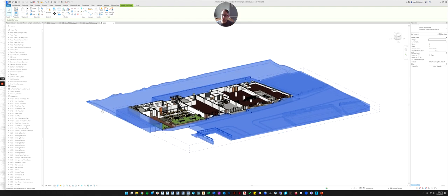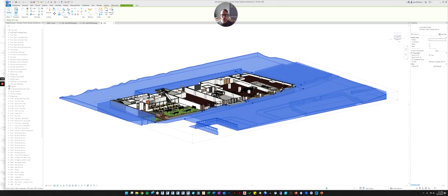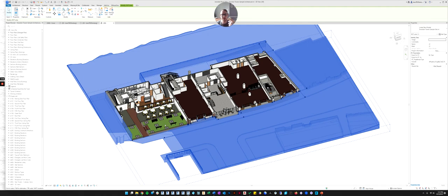As we approach this, I want you to visualize what I'm showing you here: we're going to set up the top and the bottom of the view, and the left and right, front and back of the view. We'll also talk about what things should show in a view and what things should not, so filtering model elements out of a view. Maybe you don't want to see the doors or the windows, you just want to see the walls. Maybe you only want to see floors and nothing else. We'll talk about those settings as well, so that we can have different kinds of plans.